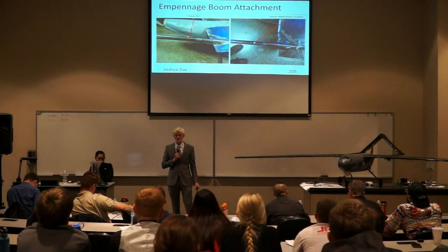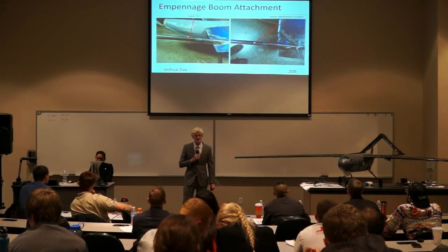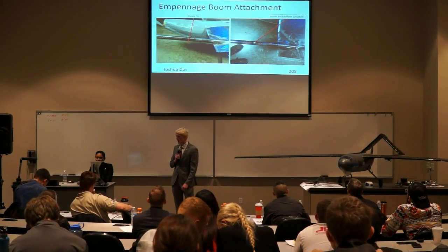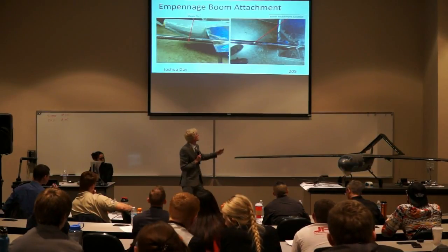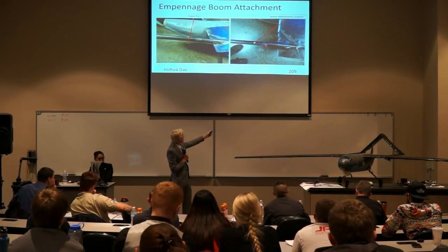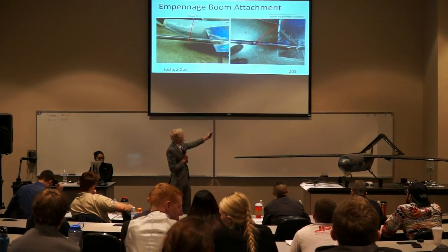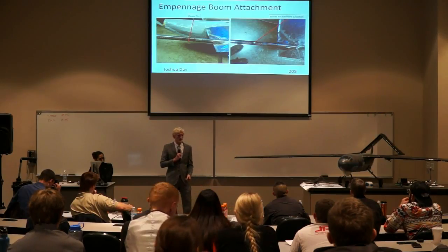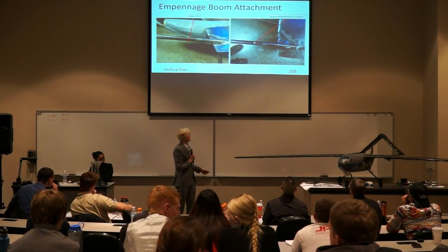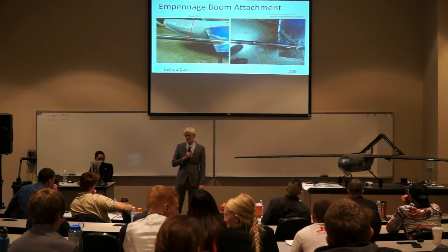The boom was attached, and it needed to be detachable so that it would fit within the 3-foot by 3-foot by 6-foot box. So in order to make that happen, we had to sand down the attachment locations so that they would fit within the boom sections, and then we drilled from the top of the boom down through the handmade sanded section out the bottom of the boom and used pins in order to attach it.